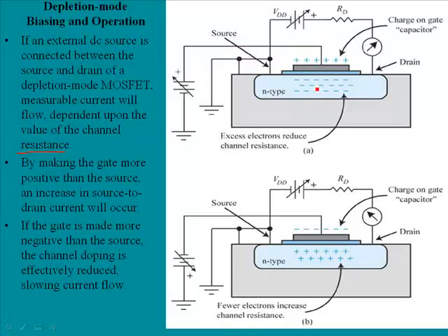The negative here will represent free electrons, and this will take that N-type material, adding many more free electrons. It will be like heavily doped N-type material, and it will easily conduct current flow, and it will have very little resistance to current flow.